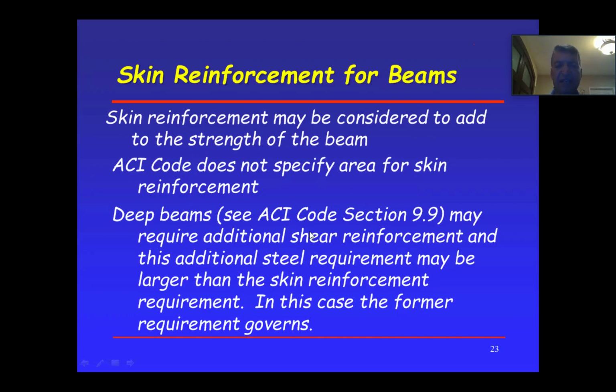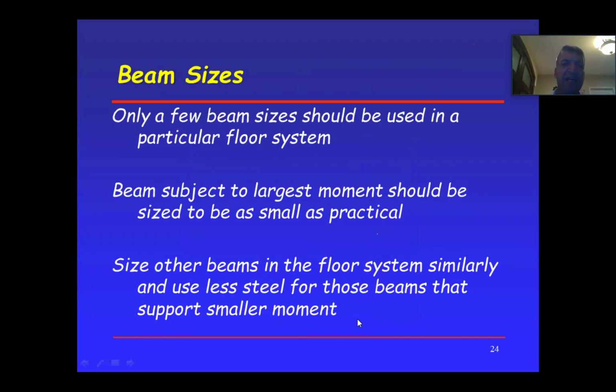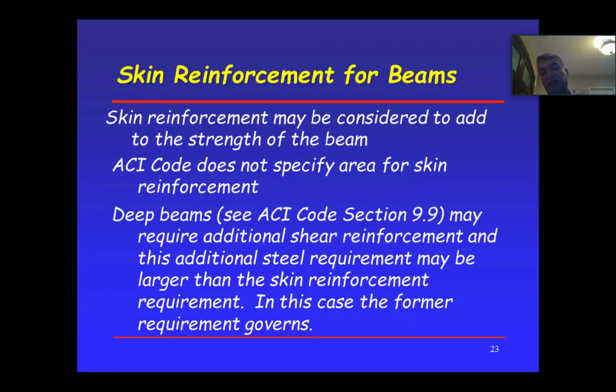Deep beams may require additional shear reinforcement, and this additional steel may be larger than the skin reinforcement. In this case, the former requirement governs. Don't worry about that. He's saying that the skin reinforcement might require a bigger shear reinforcement, which is understandable.